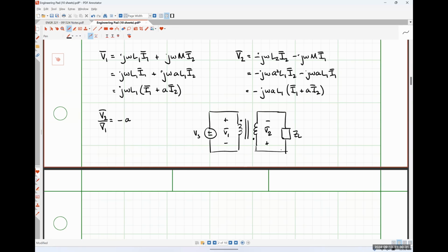As a matter of fact, in the practical transformer model, we are accounting for the losses in our coil, the losses caused by, so it takes energy to magnetize a medium, even a ferromagnetic medium that magnetizes very easily. We lose some energy to heat there. We're going to get phase shifts due to rapidly magnetizing and demagnetizing the material, because this is going to be set up with an AC system.